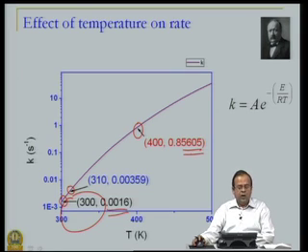So, this is why control of temperature is crucial, but this also illustrates another aspect: in design of reactors, when we are dealing with kinetics, even for first order kinetics, we could have significant non-linear behavior because of temperature variation in the system.